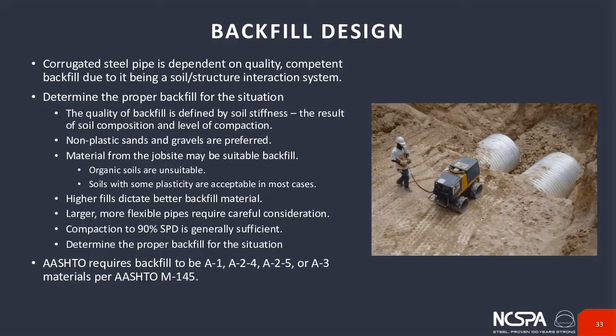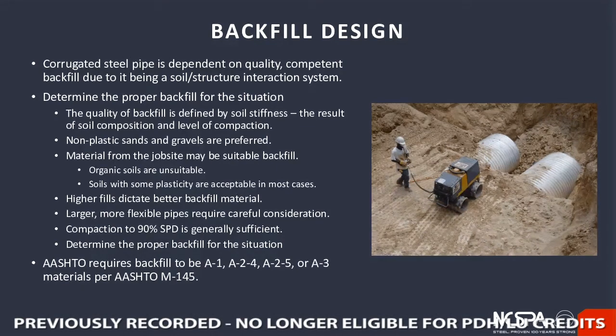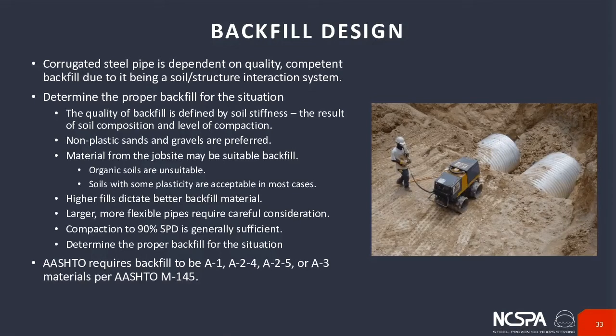It is possible that material from the job site, the in situ material, may be suitable. This would have to be evaluated on a case-by-case basis. Organic soils or peats are unsuitable, and soils with some plasticity are acceptable in some cases, which is limited in the AASHTO M145 methodologies as well.